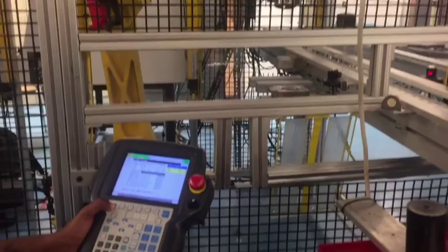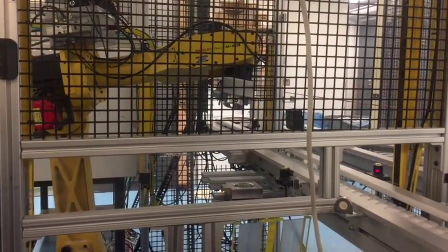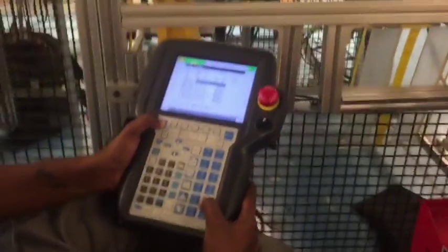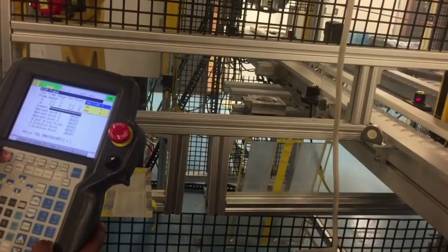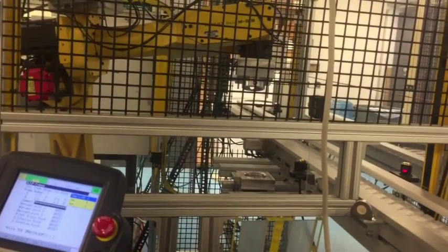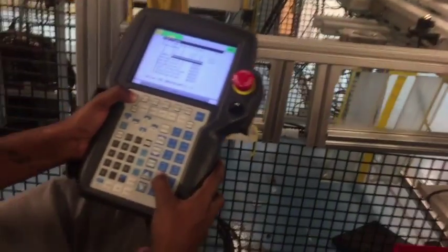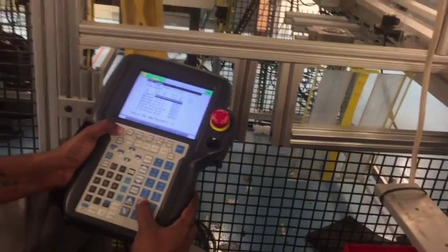This is your tool number 9. If I quickly change it to tool number 1 again and show you the difference, the whole of the tool is moving. When you're trying to operate these things, it's pretty difficult. This is tool number 1, and the whole block is moving, which is hard for you to control when teaching a program. But when I change to tool coordinate 9 and operate it again, it acts very differently. Those are the uses of tool frames, and there are a number of uses. Depending upon the application, you can find how to use it.